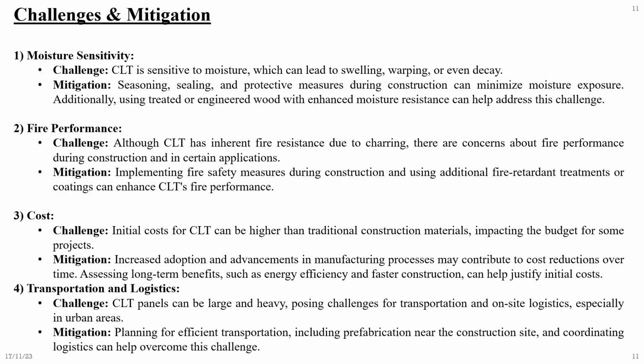Second, fire performance. Challenge. Although CLT has inherent fire resistance due to charring, there are concerns about fire performance during the construction and in certain applications. Mitigation. Implementing fire safety measures during construction and using additional fire retardant treatments or coatings can enhance CLT's fire performance.